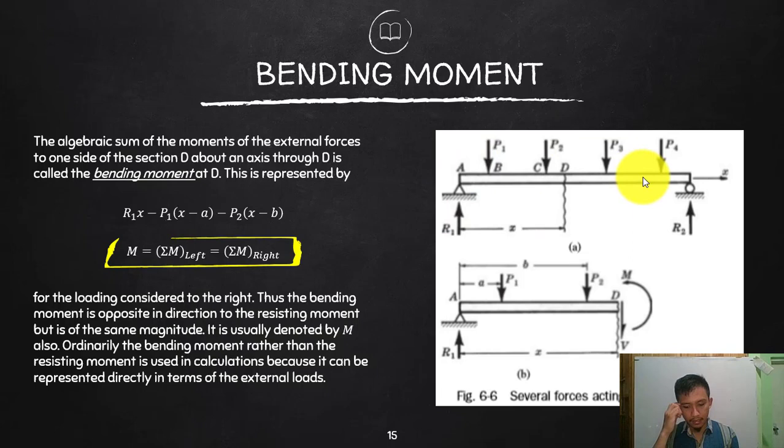As you discussed in your equilibrium, if you are trying to analyze a certain system which is static, not moving, then the equilibrium should hold, that's why we are using equilibrium, because if you summate moments and forces, that should be equal to 0. So same thing, even if I cut at that section D and then analyze this side, that should satisfy the equilibrium. Same thing if I consider the other side. That will still be in equilibrium.